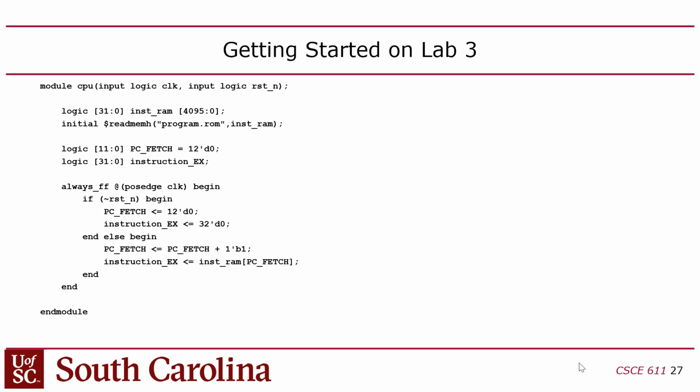Okay, so this is a good starting point for your CPU if you don't mind inlining code. This is the CPU module. This will go inside of your top module that's in the skeleton, along with your 7-segment decoders. And inside here, I have the instruction fetch logic as well as the instruction memory. I've inlined this, which is maybe a little sloppy because you could envision this as its own fetch module, but just to make it more readable, I put everything in here.